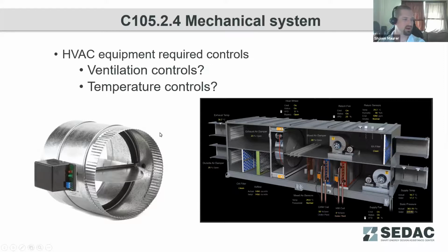So a lot to be aware of. Other things that are going to be checked are damper controls and zones for the HVAC system. Each zone needs to be controlled independently, so there should be air shut off to individual zones. So you're going to be looking at the tightness of those air dampers, making sure that they can actually seal off airflow, that they can also control airflow within the zones as needed for temperature control purposes and at minimum ventilation purposes.